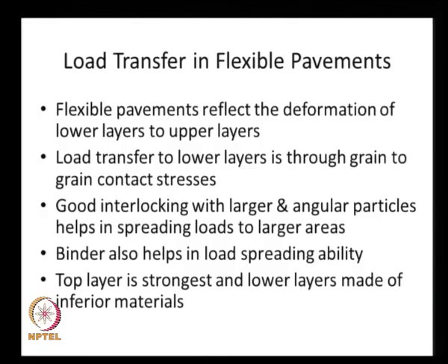These flexible pavements reflect the deformation of the lower layers to the upper layers. That is because they do not have any flexural stiffness. Whatever happens in the lower layer gets immediately reflected up to the upper layers, and the load transfer to the lower layers is through grain to grain contact between the particles.